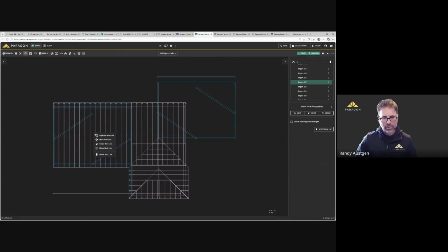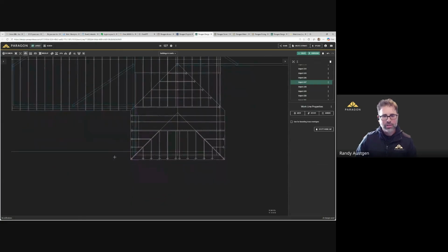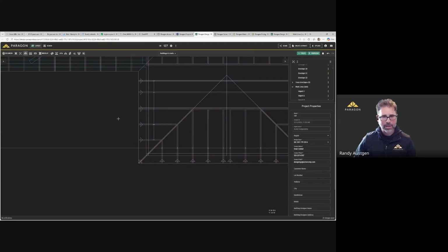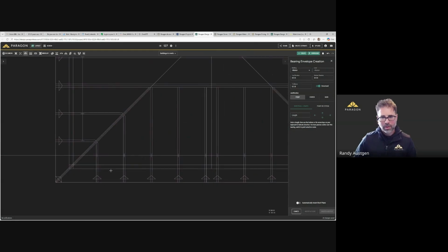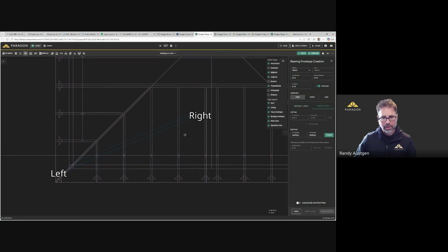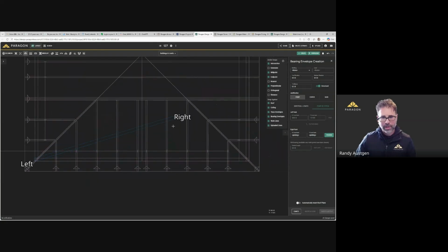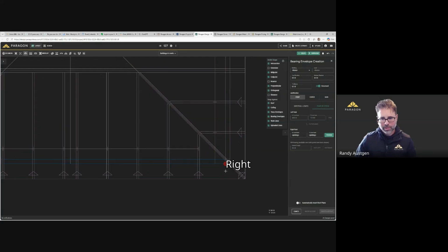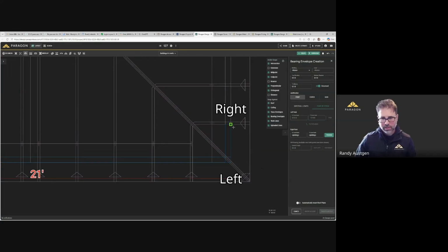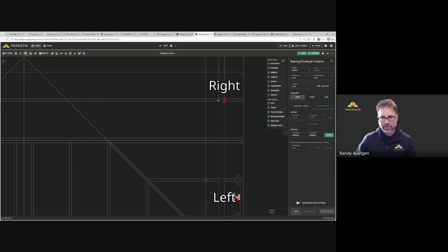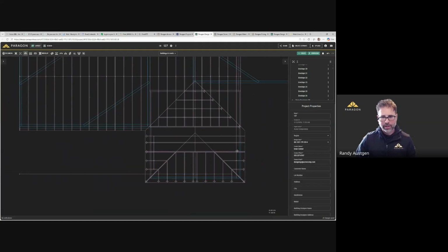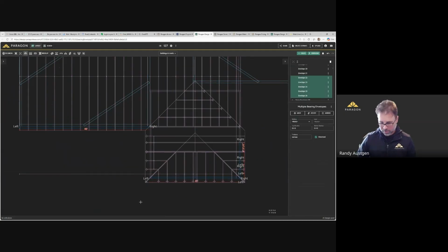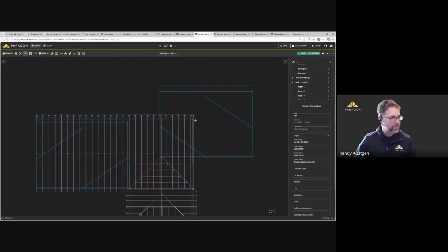Yeah, that's a great tip there. I got a mess here. So I confused myself because I had my wall visibility turned off. And here we are. That's what I was going for. So ortho is turned off right now, just so I can demonstrate kind of that pivoting. We'll turn on ortho per Tyler's suggestion. Hold down Alt, and then here I'm just putting in little wall segments, as you can see. So a couple tips there. And I'm creating quite the mess here. I'll delete that, although I think that's probably the messier part of that.